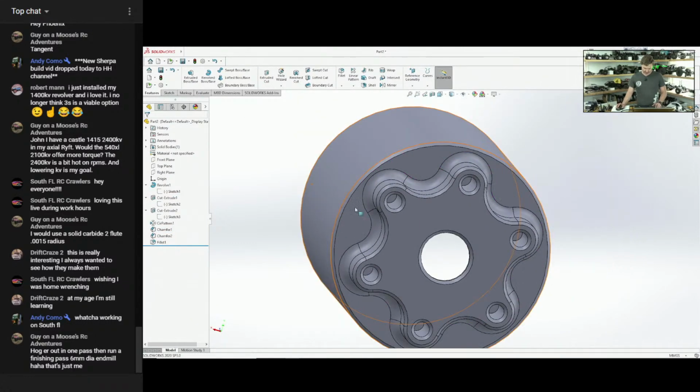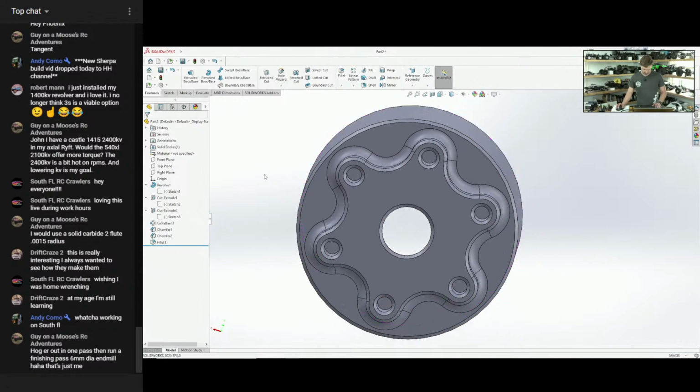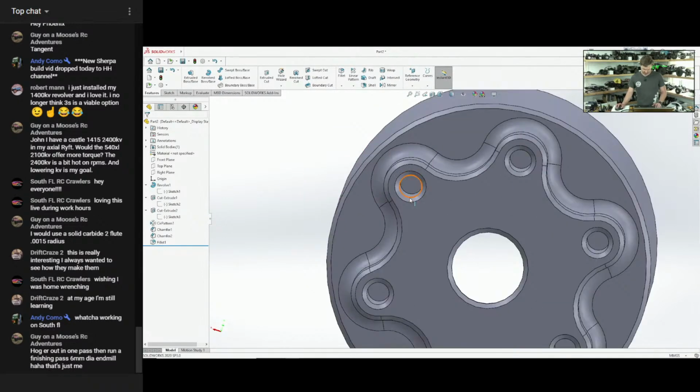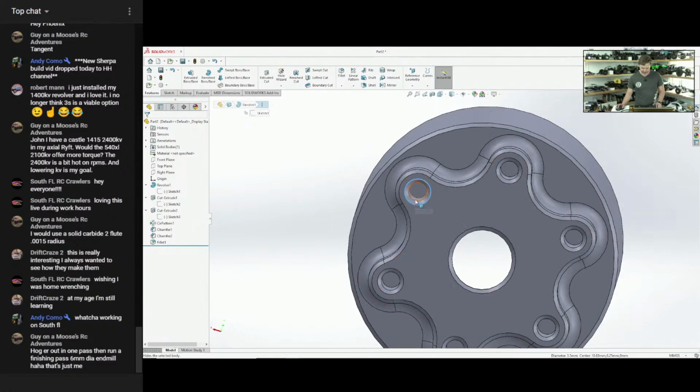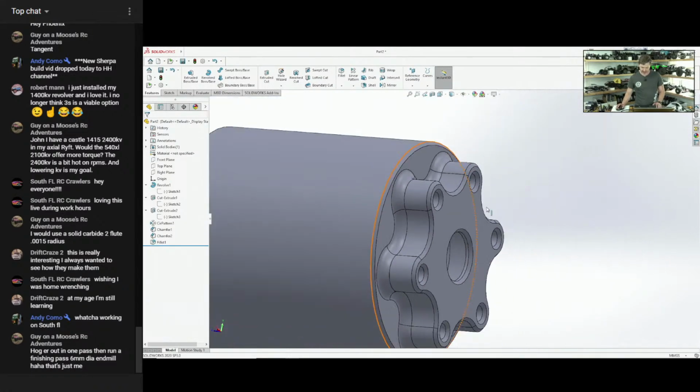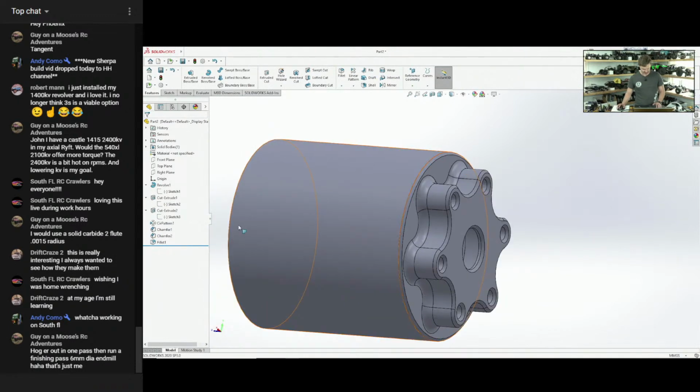You know, this is going to be threaded out essentially to the fullness of that chamfer. I would think, yeah, wait, not quite, halfway through that chamfer, because we've got a 2.5 millimeter hole and then a 3.5 millimeter chamfer edge, which means a 3 by 0.5. Yeah, that's going to be right in between. All right, so, getting a little nicer looking. What do y'all think? That would actually be able to house some motor parts.